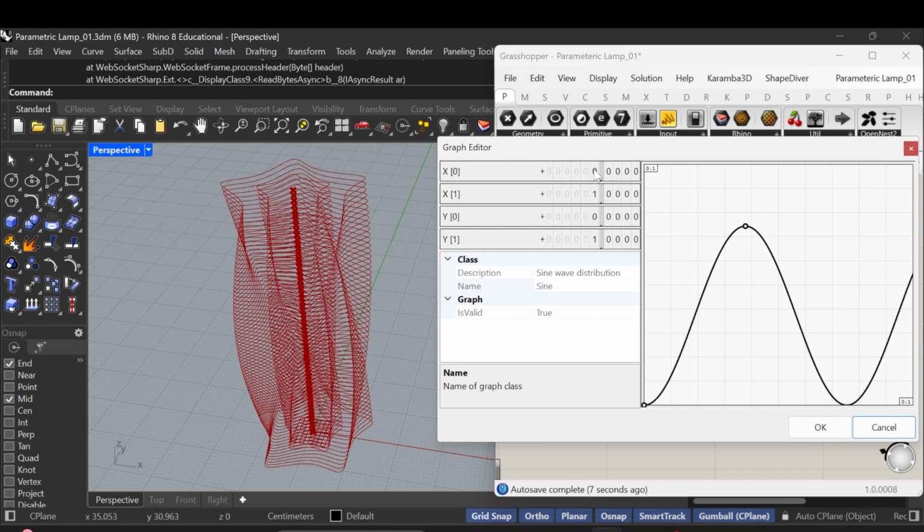I have the number between 0 and 60, because if you remember, I put the height on 60. So I'm going to use between 0 and 60. And then the scaling factor, I'm going to put it between something around 0.3 and then let's say 2.